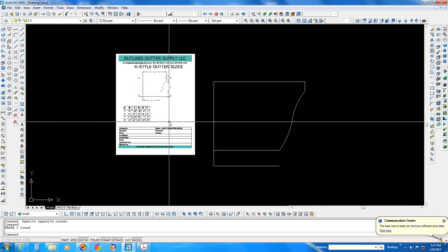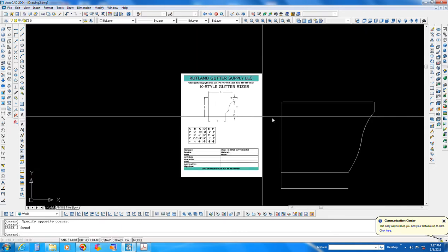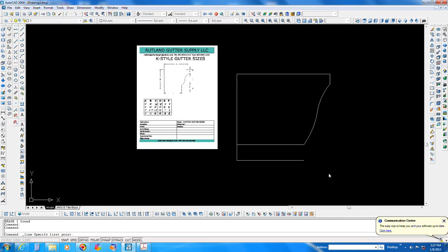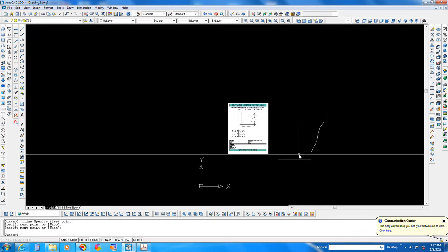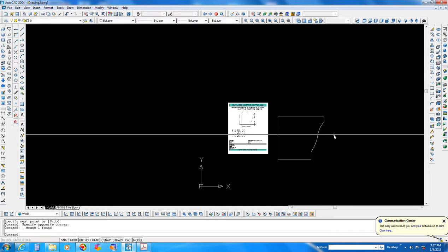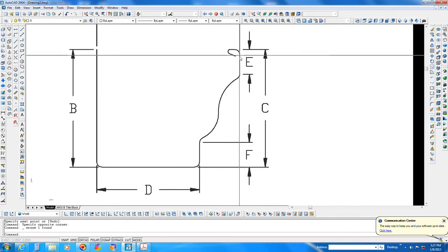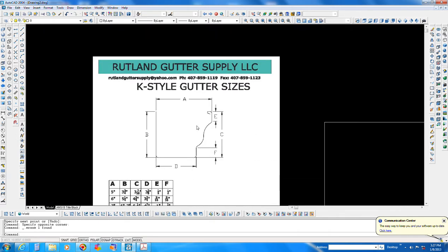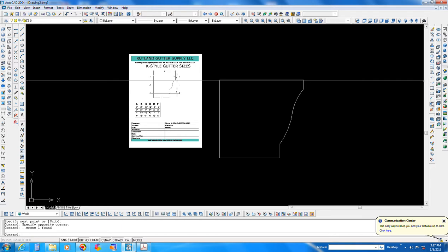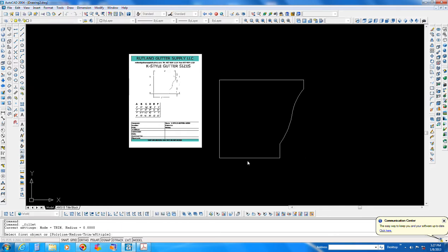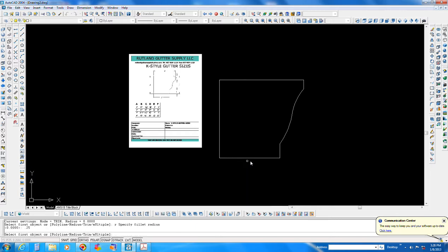We're not really manufacturing this. And then the round is actually going to be this little distance here. So let's try to give it a little distance there. We're almost done with this cross-sectional view. We can actually delete or erase that. Now let's give it a little bit of a round. We know that C comes right up to the top. We'll kind of pick something. We'll say a round of, I don't know, 1/4 of an inch. So we come over here and pick the round command, and we'll type in a radius, R for radius, and put 0.25. There we go.